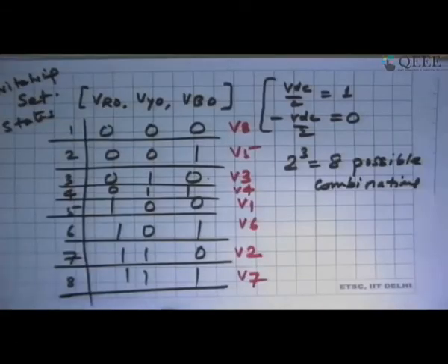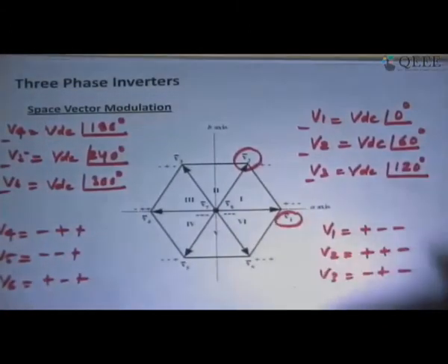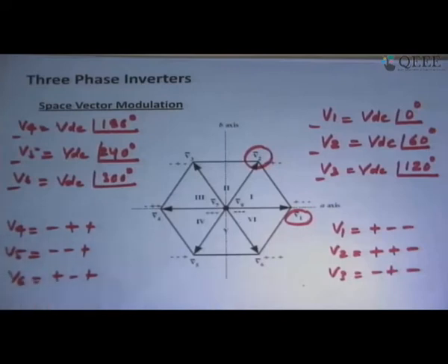So how the switching states, which is nothing but these switchings, have transformed, we would like to understand how it happened, how the switching states we are calling V1 to V6 and V7 and V8 have got these angles associated. For that we have to use space vector derivations.